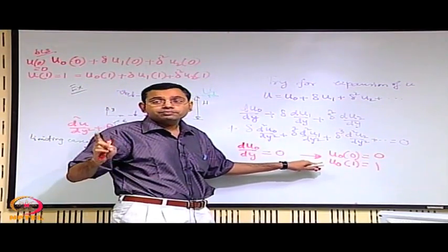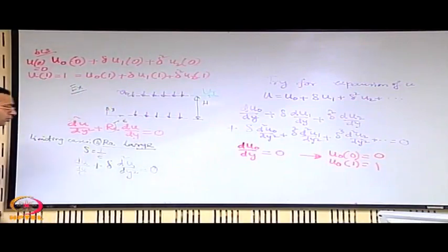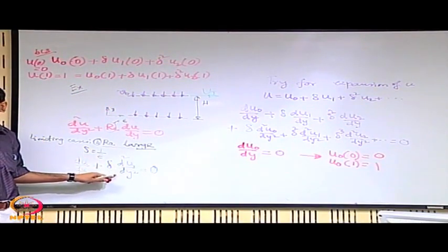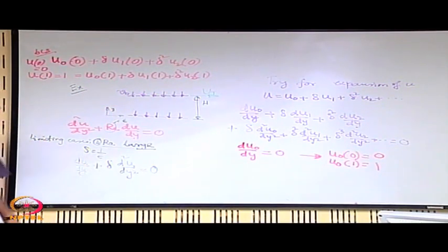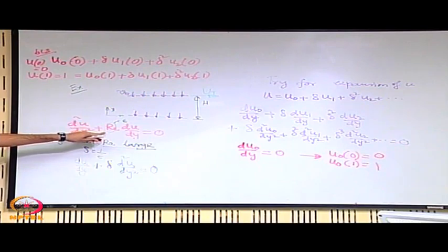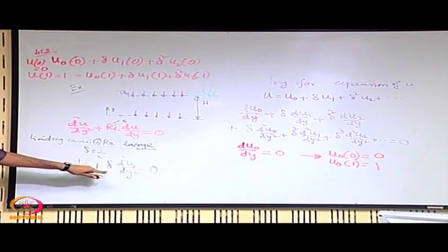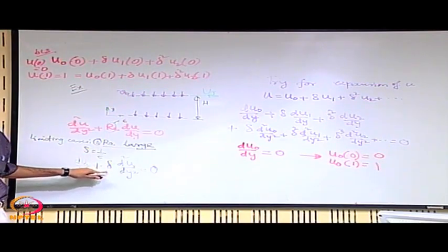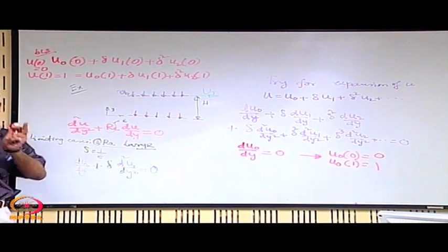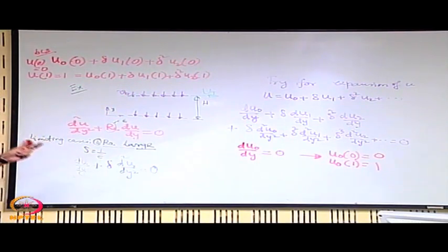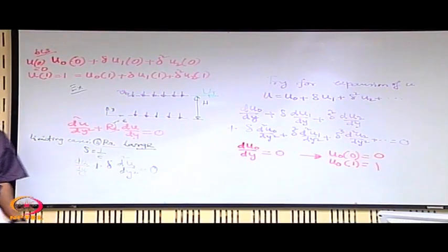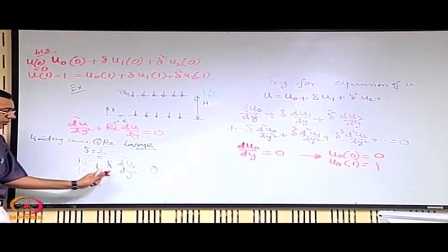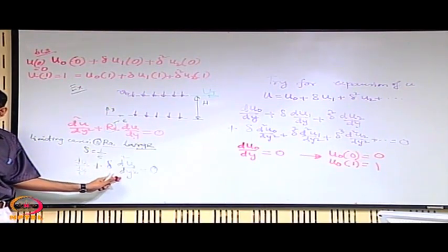That is one of the basic mathematical reasons why you cannot neglect this term altogether, although the boundary layer is thin. This has something to do with the thinness of the boundary layer, because this is 1 by Reynolds number. We know that in boundary layer theory Reynolds number is large. So this has some sort of analogy with the boundary layer theory, fully analogous mathematically, partially physically, because you have a small coefficient of the viscous term.